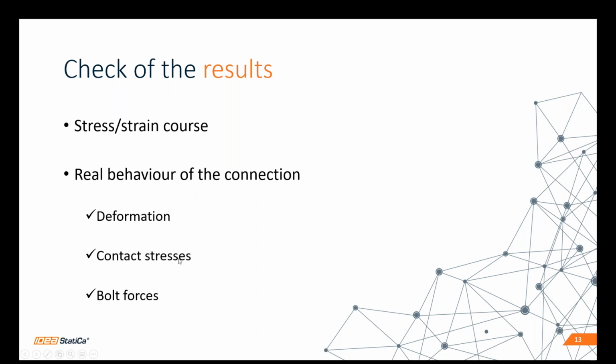We can display also contact stresses between parts, so where the plates meet, then we could check, or where we expect it should be in contact, we can check it really is, and we can see the stresses in there. And also when we expect some bolt forces to be there, we can check exactly what values, and also graphically where is the maximum, where is the minimum.